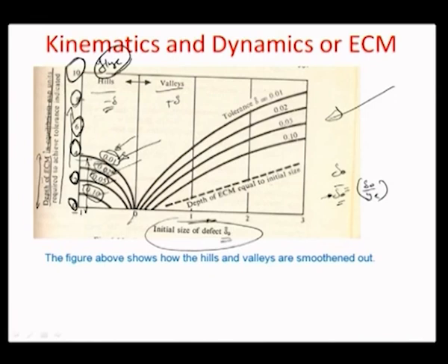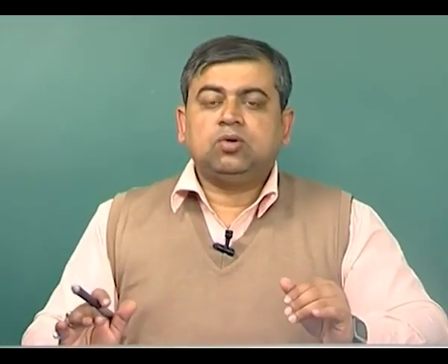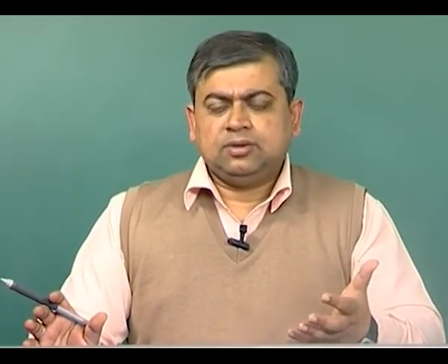So, therefore, it is a very clear cut specification sheet which has been generated, which mentions from what initial size of the defect, how much y has to be moved by a particular workpiece towards the tool, so that you can achieve a certain percentage of the equilibrium gap as the tolerance size. So, that is how the whole plot has been generated, and this plot can be used as a sort of thumb rule for a process engineer who is working in an ECM process.